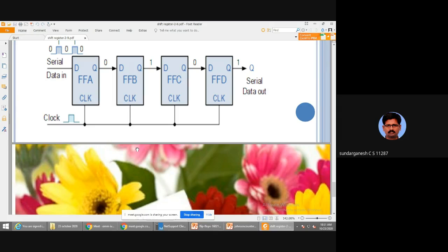Now it doesn't have any data, so this will move here, this will move here. In the third clock pulse, I get that. So in PISO also, we get 3 clock pulses. If it is SISO, it is 5 clock pulses. SIPO, 3 clock pulses. Here also 3 clocks.